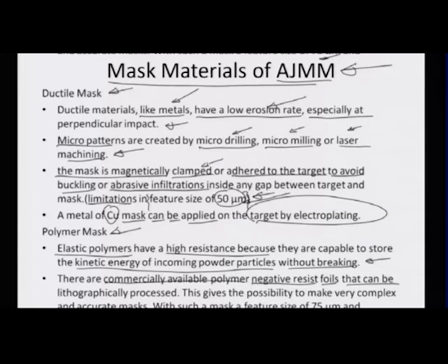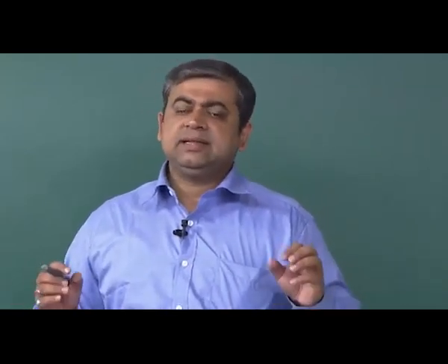The resist actually, if you are using S1813, comes off very easily from the substrate surface once it is dipped in acetone. Okay. And for other resists like SU8, there are some stripping agents which are commercially available which can also be used. So another approach is that you create a layer or a foil of this resist material, photoresist material, and then suitably expose it and create vias and cavities in a photo patterned manner inside that foil. Okay. So both approaches are good enough, direct coating as well as foil based coating for the mask making.